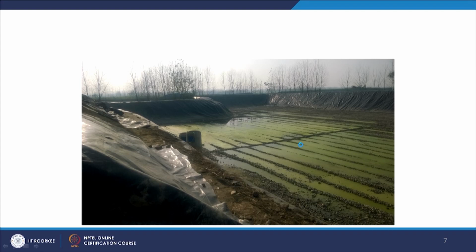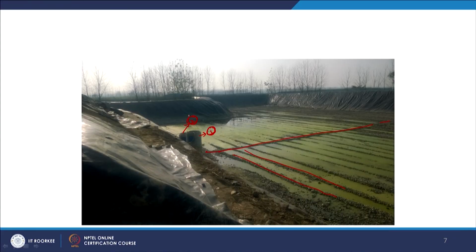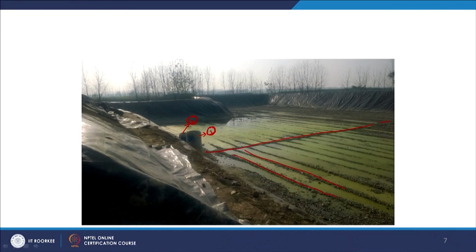So here is another picture from another angle. As you see, all these are the leachate collection system pipes. They are now collected in this single pipe, and then they are transported to these sumps here. Here I see 2 sumps. The first one is the sump that is connected to the upper or the first leachate collection system. The second one is connected to the secondary leachate collection system or the leak detection collection system, which is beneath this particular set of layers.